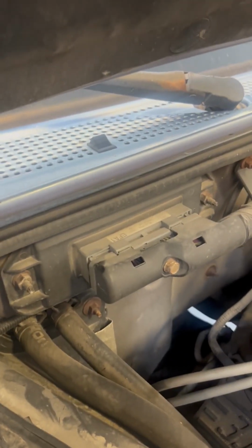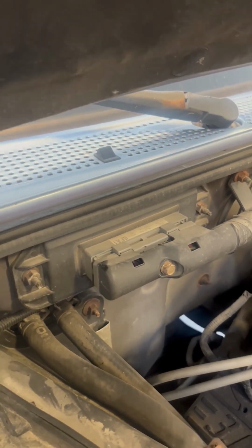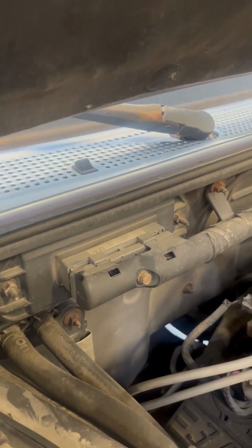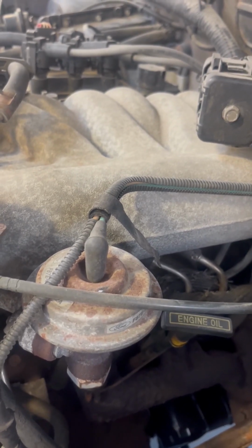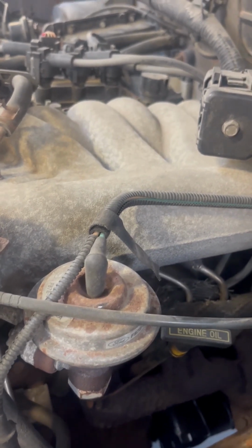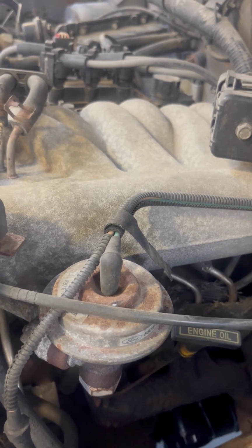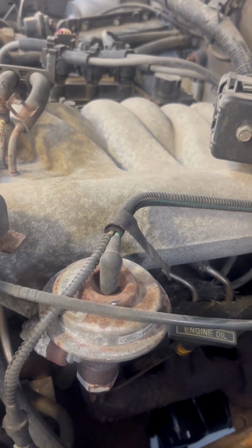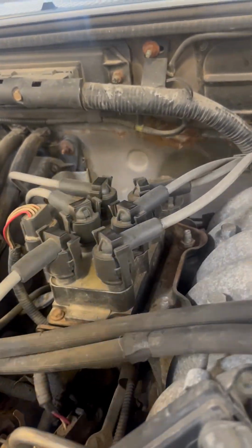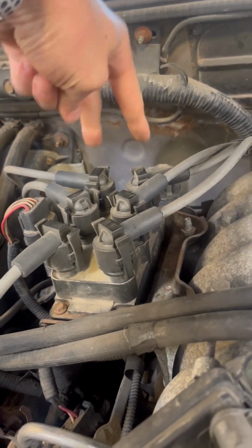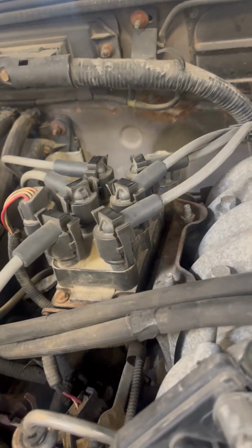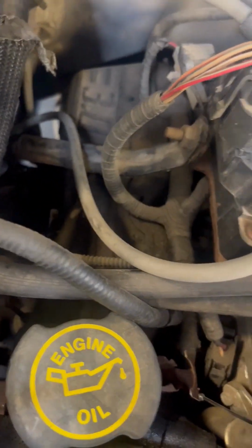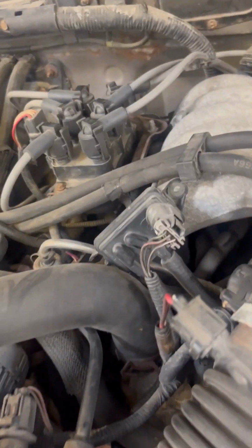Here is the location of the PCM. It is the brains of the vehicle, takes all the inputs and figures out what to do with the outputs. This is the EGR valve. It recirculates unburnt oxygen and fuel vapors to create a cleaner burn, and the sensor on top is an input to the PCM. This is the ignition system. It is a coil pack that sends spark through 2 wires at a time, through the spark wires into each spark plug in all the cylinders.